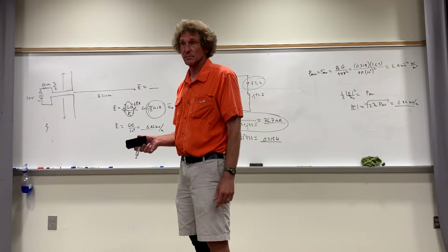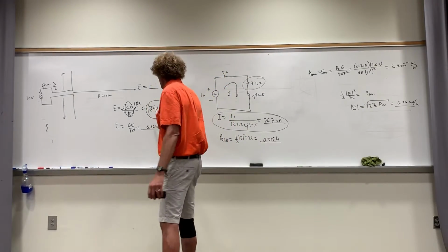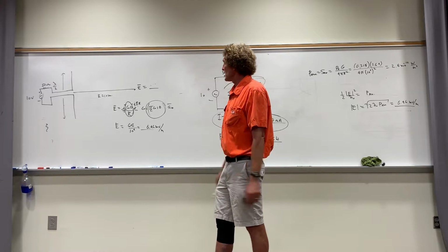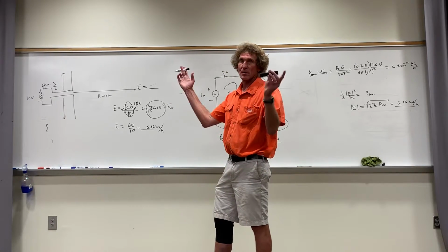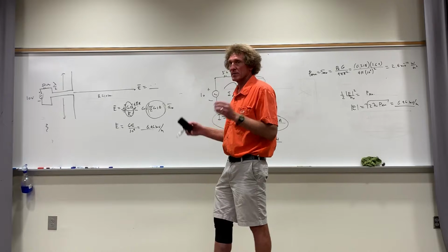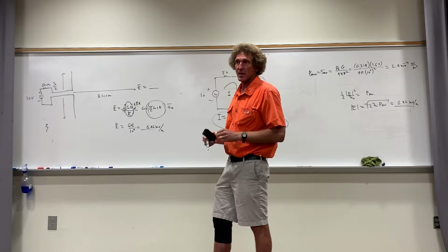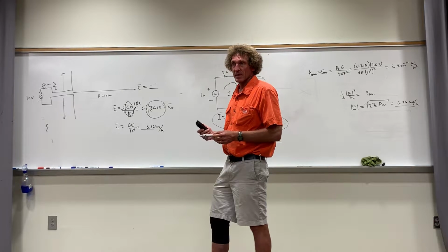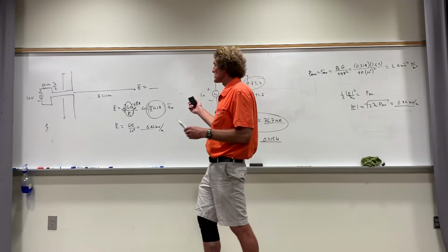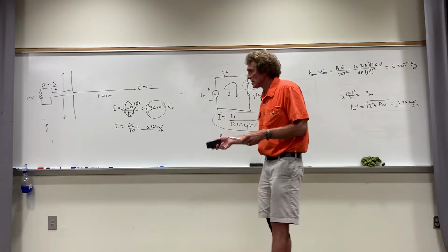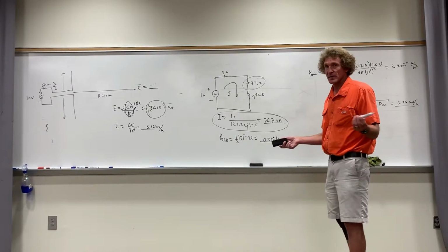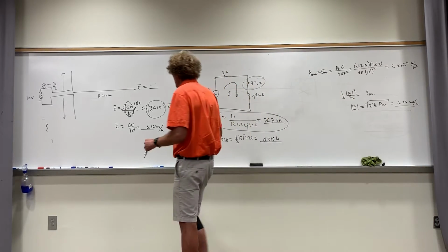If you were looking at it at some angle, you would just plug in the angle, and then you've got to evaluate that nasty cosine term. The e to the minus j beta R is still just going to be 1 in magnitude, so ignore it. The j, ignore. It's of no value. But I would go that route if it was me doing a test. Yours is more complete in the sense that you calculated all these intermediate terms that may be of interest to somebody, power densities and stuff.